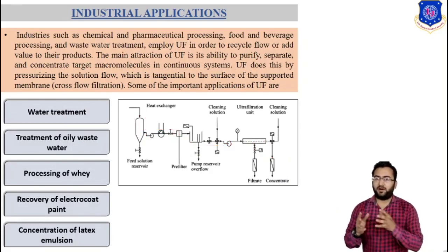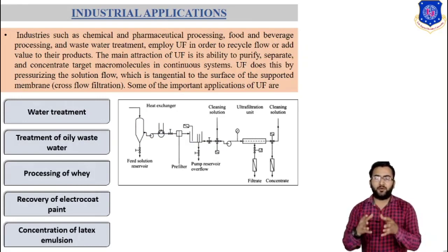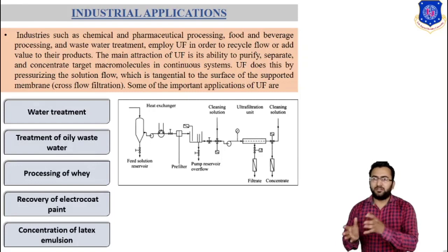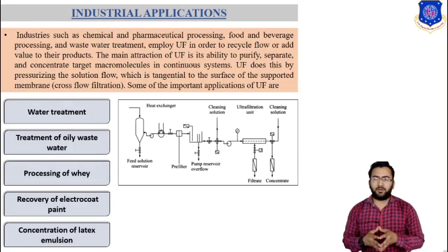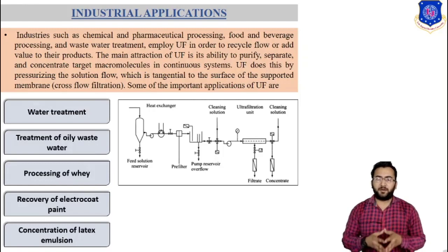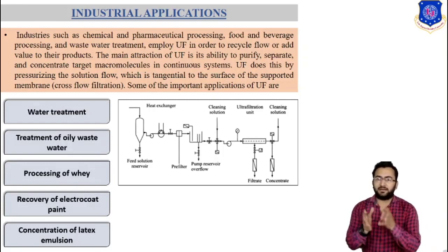The second application for ultrafiltration is processing of whey. Whey, a byproduct of cheese manufacturing, is composed of roughly 0.6% true protein, 0.2% non-protein nitrogen, 5% lactose, 1% salt, and some lactic acid, and the rest water, at pH between 3 to 6. It also contains trace amounts of casein fines and globules and a large population of bacteria. Ultrafiltration retains two principal proteins, lactalbumin and lactoglobulin, with a Dalton size of 36,000.